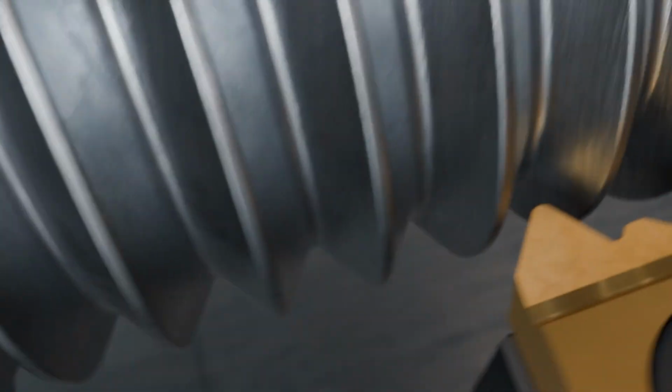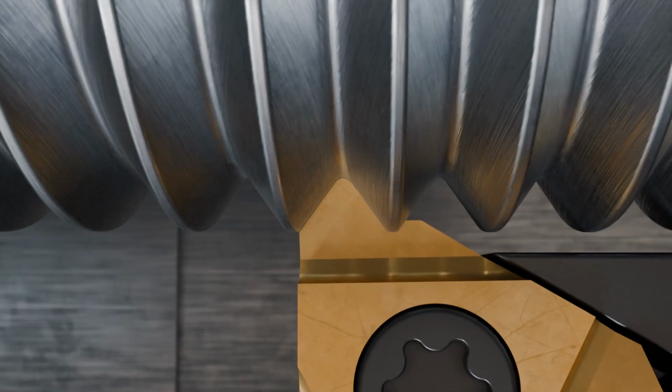In the case just discussed, a so-called full-profile thread insert was used. This cuts the entire thread profile, including the thread crest with the corresponding rounding. In this case, the initial diameter of the workpiece must be about 0.05 to 0.07 mm larger than the nominal thread diameter before thread cutting. This allowance is then automatically turned down to the nominal size in the final pass by the full-profile thread insert. Since the thread is fully cut, a separate full-profile insert is required for each thread type. For a large number of different threads, this requires a correspondingly large tool inventory.